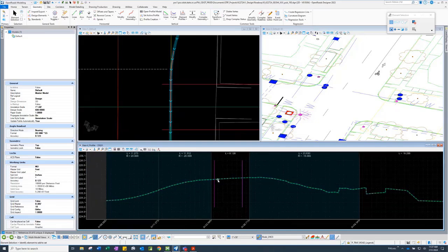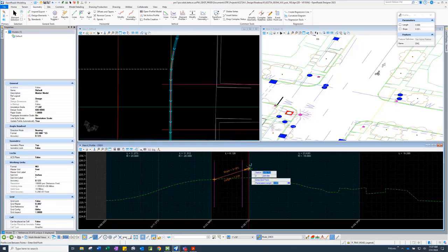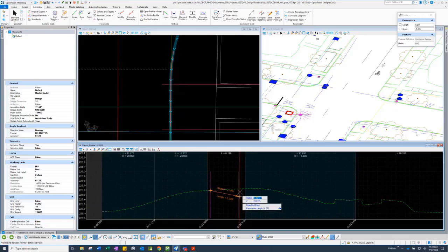So here, because this project is working off existing, this is an example of a construction line for this ramp opening. I need to make sure it is less than 1.5 or less than 4.5% at the gutter. Now remember, this is the gutter line. So I would come up and draw another 2-point line. I can snap it to this gutter, and there are a couple things I can do. Would you hesitate for just a second, because you are using the vertical line between points command. Is that right? Correct.